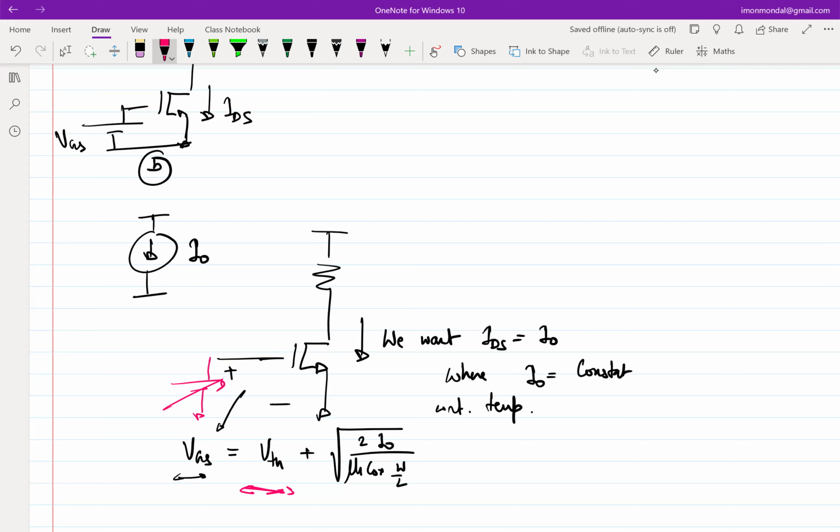Yeah, but connecting both of them means? Yeah, right. So I'll tell you what's the issue. The issue is if I do this, how do I then connect the input? Because gate and drain are shorted now. Because when I am applying an incremental input, I want the gate and the drain to be isolated, isn't it? Because the input has to go to the gate and the output will come from the drain. But by the way I have generated the bias, I cannot do that. That is actually one of the ways people do, but not for this course.